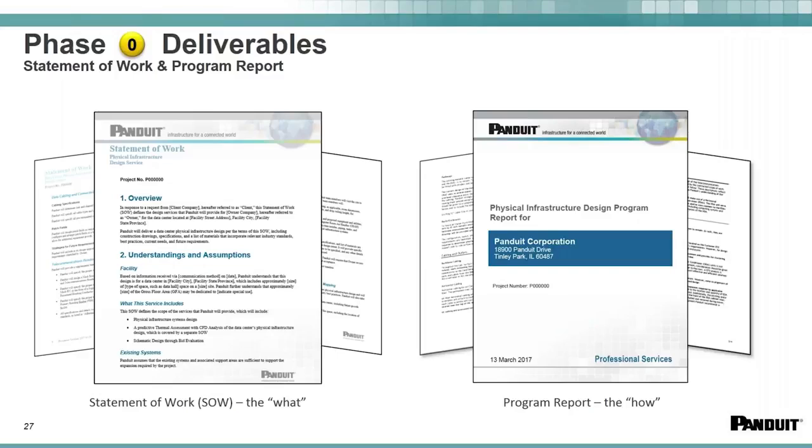And all this will be done by meeting with the owner to determine the requirements, walking their facility, looking for any requirements, and then identifying the type of solutions that can be needed. So it'll go down to the level of showing the cable media selection, the topologies, redundancy requirements, looking for available pathways, looking for the locations that we're going to be putting all the components. And so all of that gets described in words in the program report.